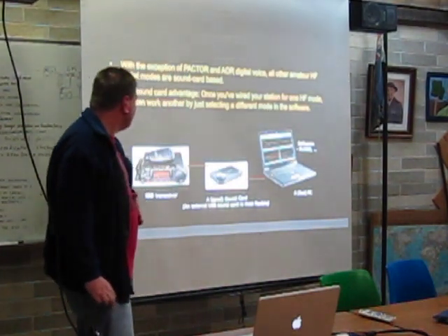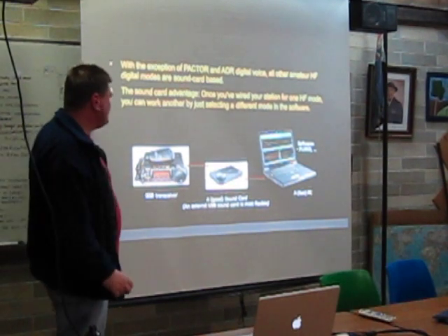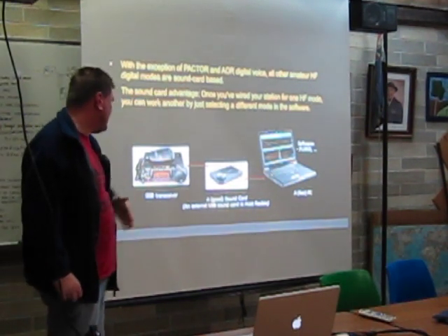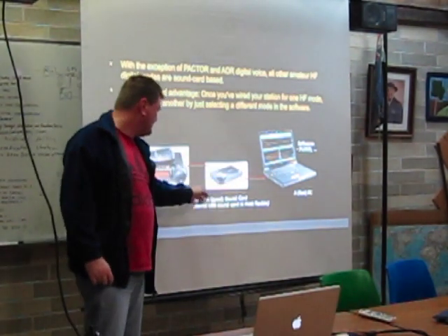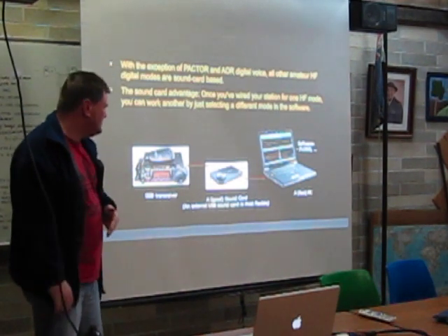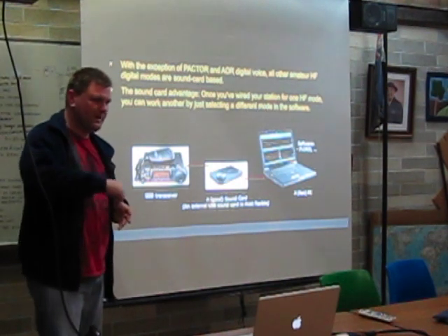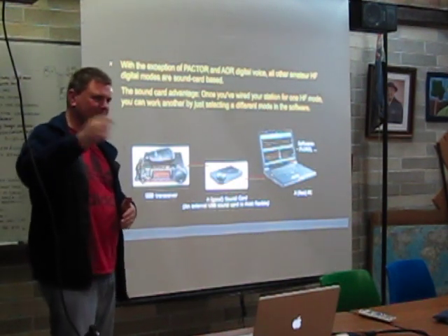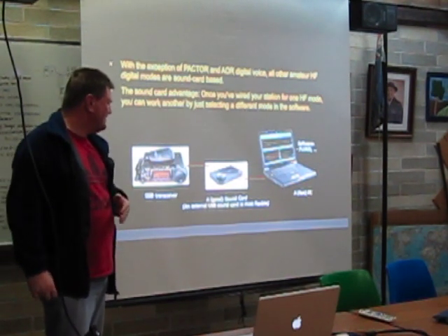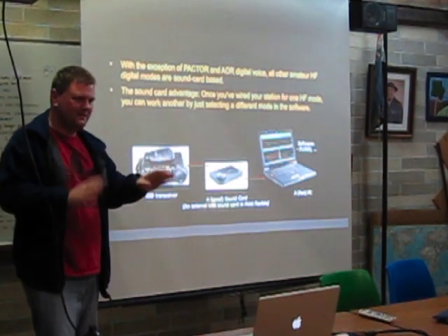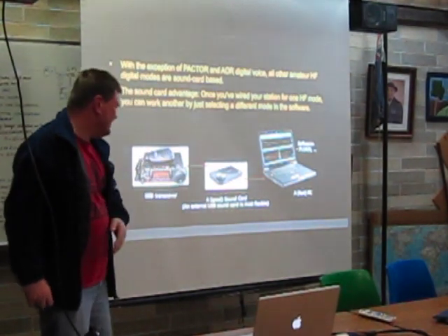Okay, so except for the Pactor, I already mentioned you need some special hardware. All these other modes I've talked about, you can just use a sound card on your computer. So have a radio and a sound card, which may be built into the PC, or it's usually better to use a separate external one. The reason is because often on your PC you hit the wrong button and it has bells and whistles, or email arrives, you get some ding. You don't want that sort of stuff going out over the air. So generally you keep the sound card in your computer for playing all that noise that normally gets generated, and use a separate sound card for the radio communication.